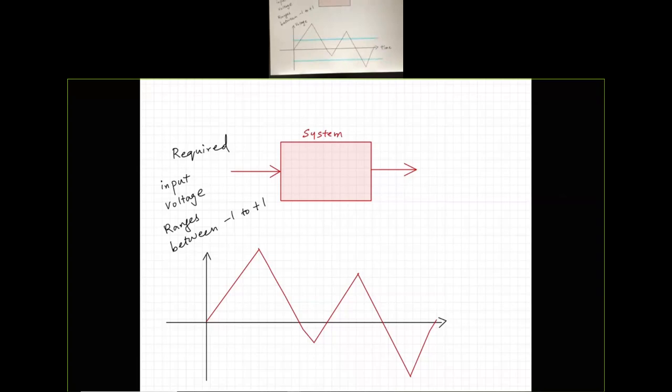So if those two are 1 and -1, and if I was trying to satisfy this requirement, so that my inputs only fall in the region of -1 to 1 volt, I have two simple choices. One is I can squeeze my waveform such that this falls at that point and this falls on this point.